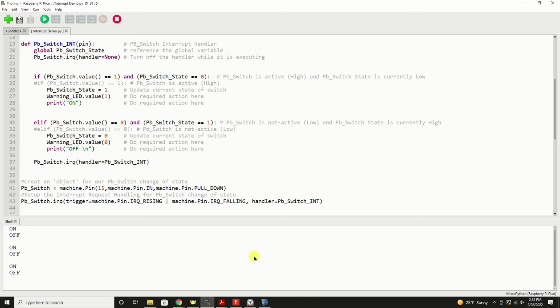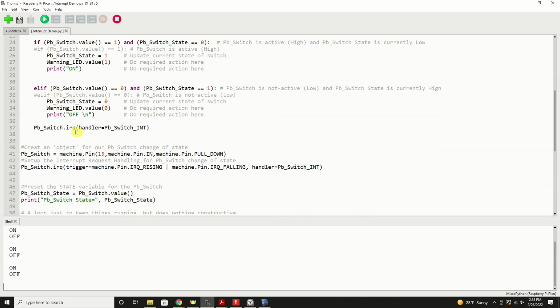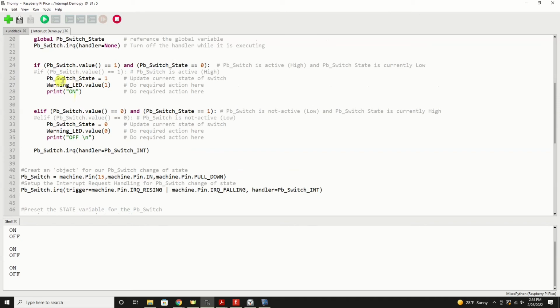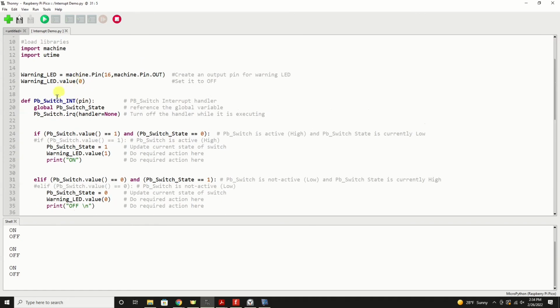Isn't that much cleaner than what we had before? With just a few lines of code, we can solve a very complex, cumbersome problem and not go through the, I'm going to call it a hack, of just throwing a dwell in here to let the switch bounce pass or whatever the case may be. So that is the importance of using that state variable, why it's a global.